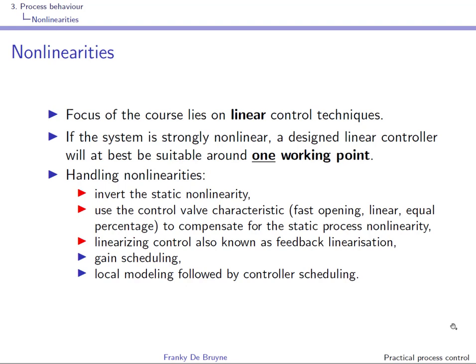If the nonlinearity is static, what you can do is invert the static nonlinearity, and one way to do this is to use the control valve characteristic to compensate this static nonlinearity. This is explored in the next slide that I will leave for your information.